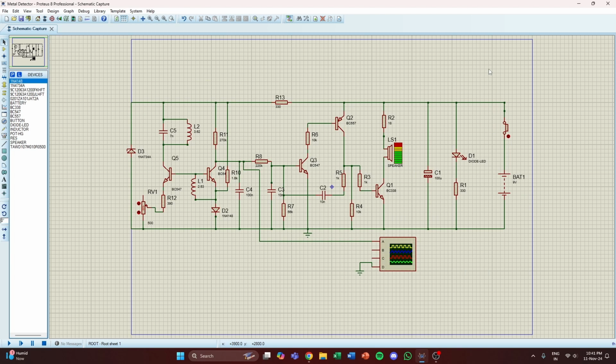When a metal object is placed in the center of the coil, some of the flux enters the object and causes eddy currents in it, and this flux is lost. The receiving coil does not get the full amplitude of flux, and the transistor is turned off a small amount. This increases the voltage on the collector of the second transistor and is a tone to be produced by the next three transistors. Now we come to the second block, the voltage controlled oscillator.